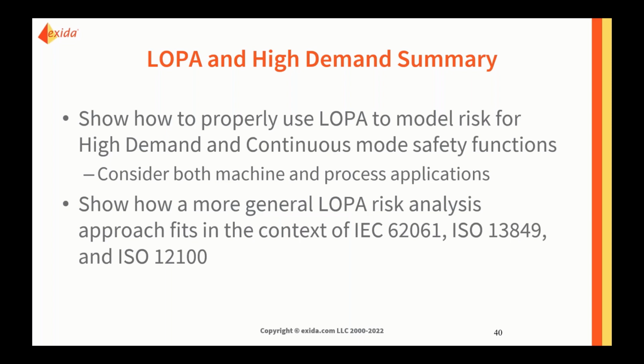All right, so next, why is LOPA termed semi-quantitative? Semi stands for partially quantitative when you're using the order of magnitude protection layer simplification. That is, each protection layer gives you a full order of magnitude risk reduction, or you don't take any credit at all. So that very rough quantification is what we use the term semi-quantitative to mean in all of this.